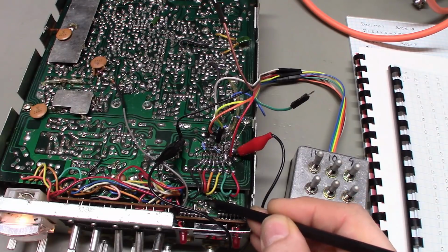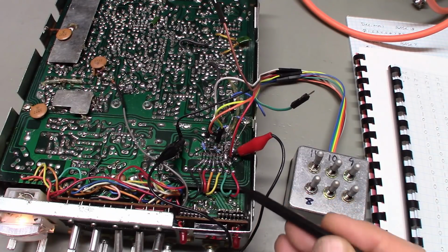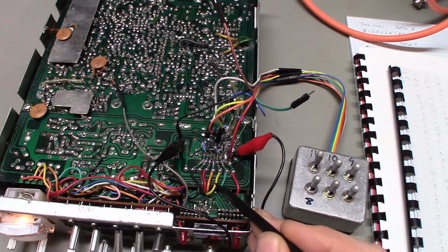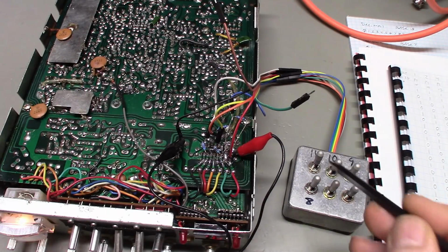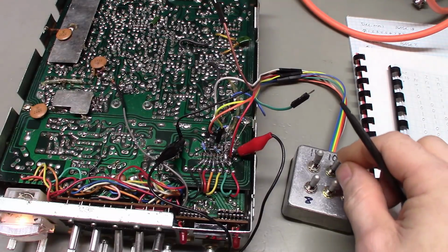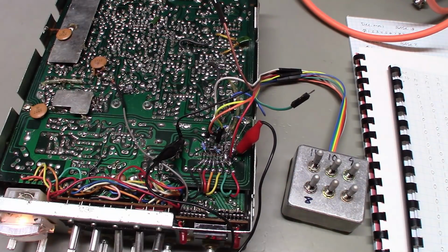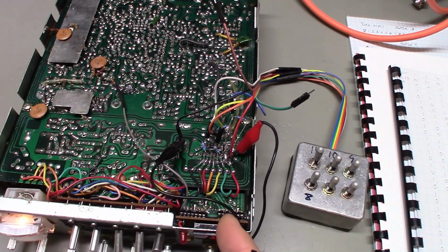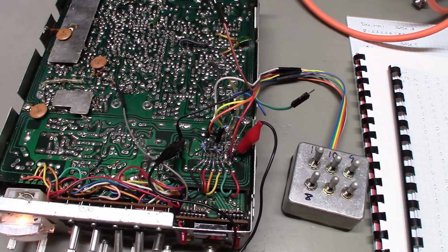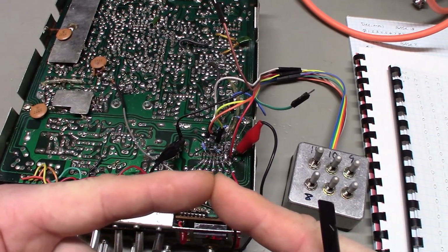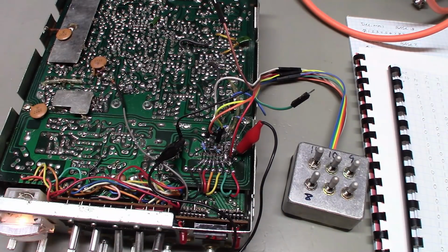Well, if it's sending a logic level high, or a 1, to the PLL, that means there's voltage present on this thing, okay? If you just take a wire and attach it to ground there, you've now created a dead short. And you're going to let the magic smoke out of something, either out of your box, out of the channel selector switch, or something in the radio. You're going to let the magic smoke out if you go touching positive and negative together. We don't want to let the magic smoke out. So that's what this resistor does, okay?